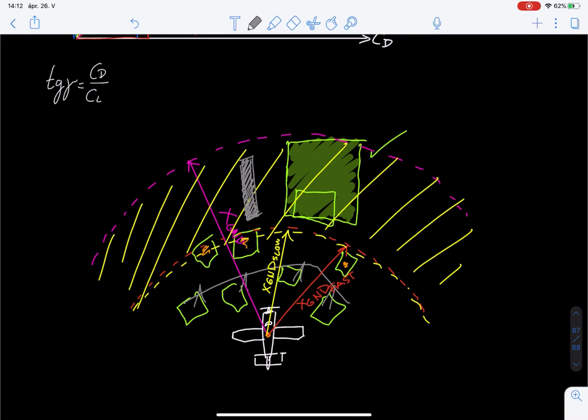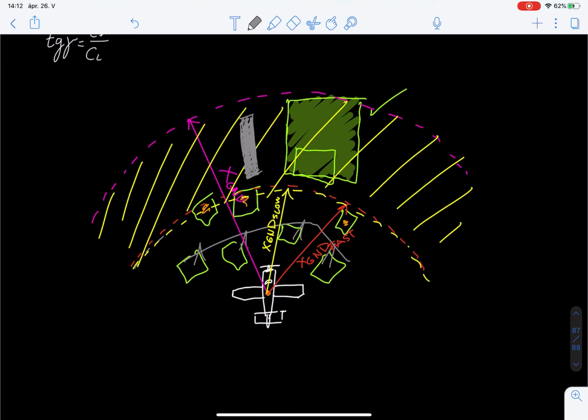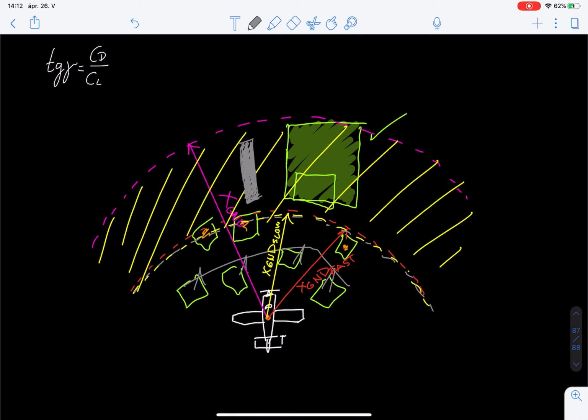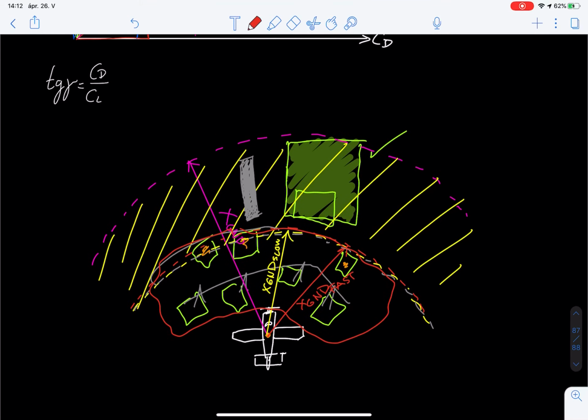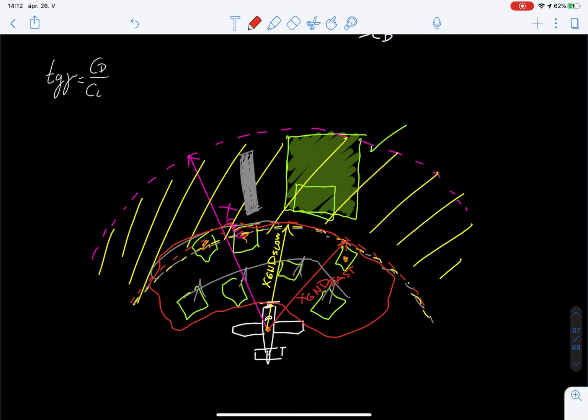So maybe the runway is still within reach if you fly with the correct speed, but if you fly at other than the best glide speed, you're not going to make the field, you're not going to make the runway. You're instead going to have to make a forced landing, and maybe much worse, you'll be forced to make the landing in much worse conditions than you originally would have anticipated, and this is what's most critical, than what the airplane's aerodynamic conditions would have enabled.